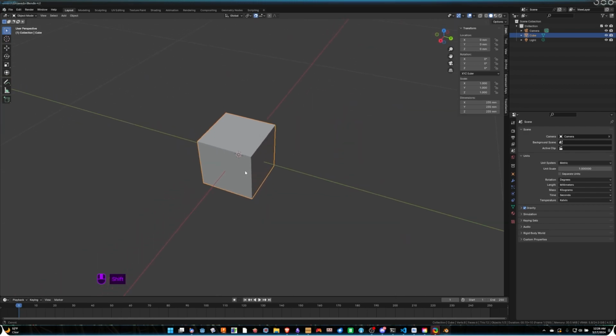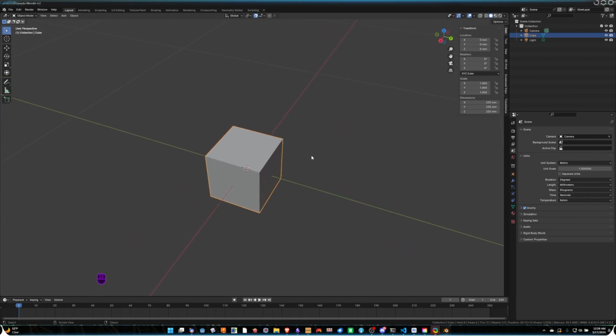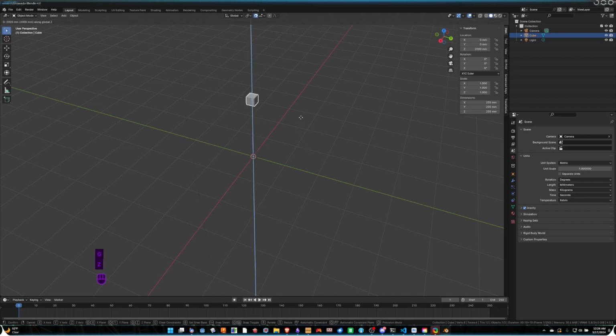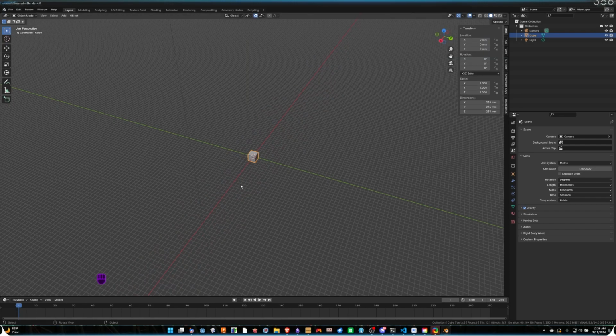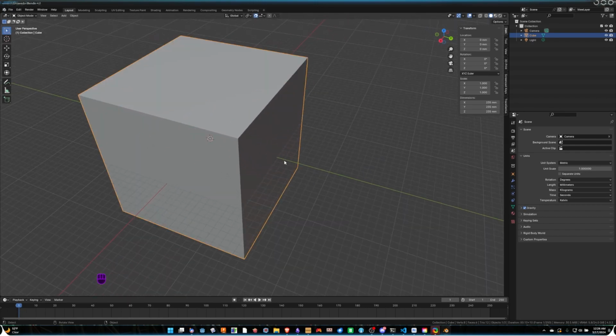So let's change the size of our increments, because you notice that it's moving about a meter at a time right now, which is far too much. You can see how far it's moving over here in the transform tab inside of our different location settings. So we want to change the increment. Let's change it to, well, it's 1,000 millimeters per meter. That's 3 decimal places. You notice the grid changed? And if we zoom in, our grid subdivides.